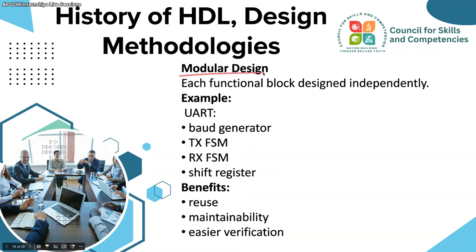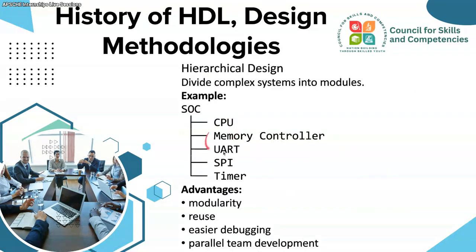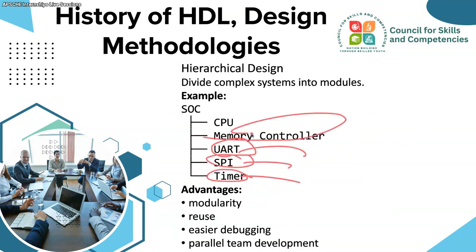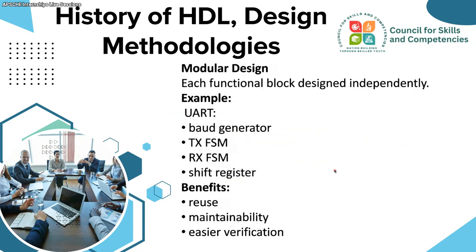So what is this modular design? Each functional block is designed independently. Okay, so you can go and design this UART independently, SPI independently, timer independently, memory controller independently, CPU independently. That is where the modular design comes. So UART, that is one example.